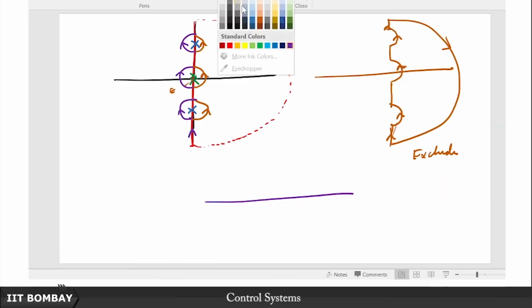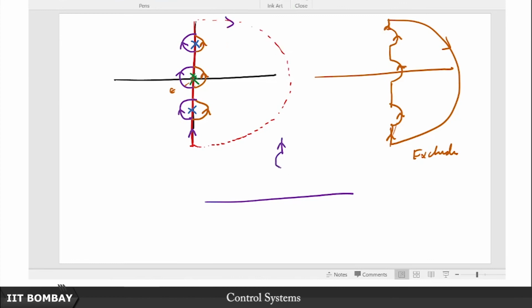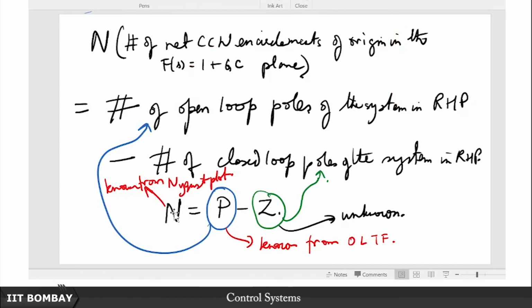So what we then do is, the other choice is this, and you include the fellow here. And you will see that if you do careful bookkeeping, carefully you keep track of how these contours are being negotiated, you will still be able to draw the Nyquist diagram and correctly deduce this N, and once you have drawn this, deduce this N, then this Z can be just calculated by this.